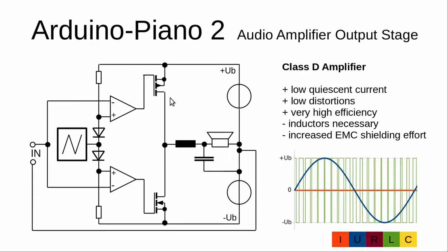But this switching time is very short, and in the end, in the middle, the power loss due to the switching is very low. To get the variable output voltage, PWM modulation is used. At 0 volt output, the positive supply voltage and the negative supply voltage are turned on each 50%.